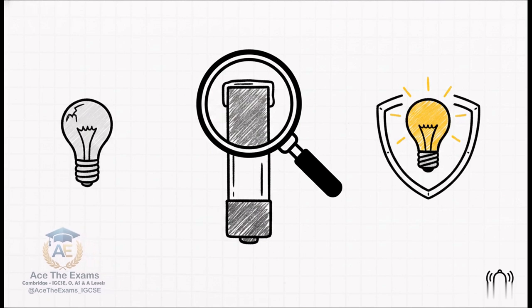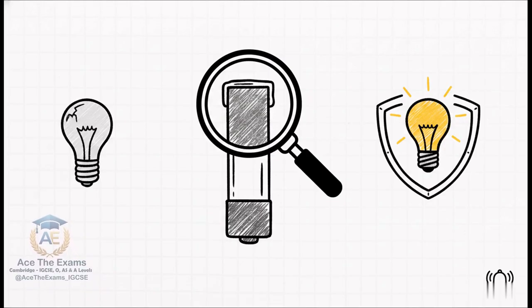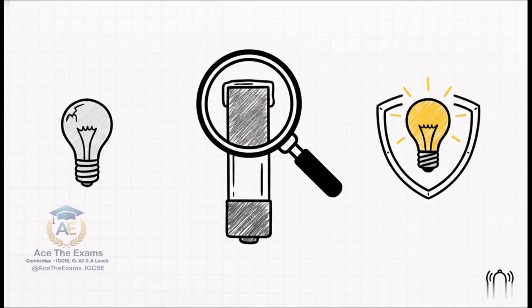Boom. Time's up. Did you catch it? The point was the 10 amps. The evidence was the P equals IV concept. The explanation was why the 13-amp fuse is slightly higher, and the link tied it directly back to the safety context of the question. That is how you decode command words.